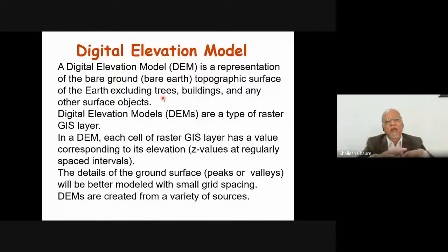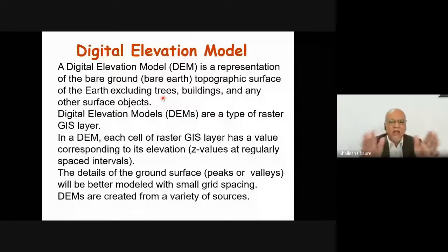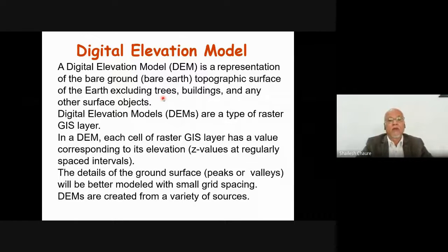So using that surface, we can compute the volumes, the cut areas, the cut volumes, fill volumes, and if you add something to that, how the final level will be and how it will appear. So for that, we perform various kinds of topographic surveys. And you know the topographic survey is a tedious, time-taking task. But of course, civil engineers are forced to do that because they want high-resolution data. But nowadays, some modern techniques are coming that can save a lot of our time, and not only does it save time, it can create high-resolution data also, even for civil engineers.